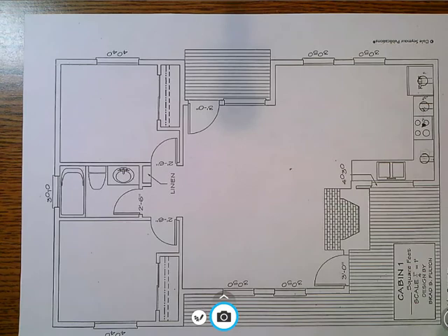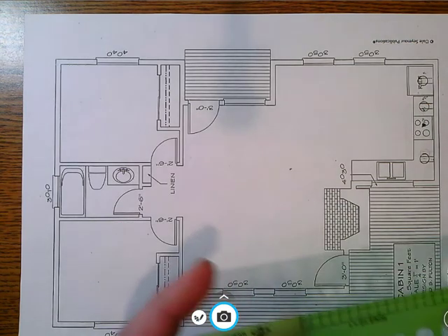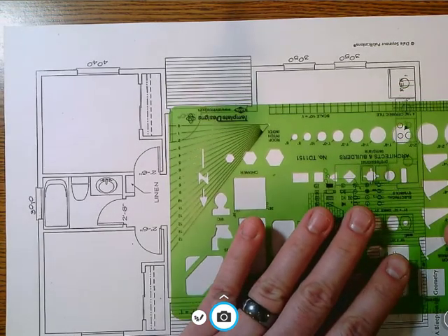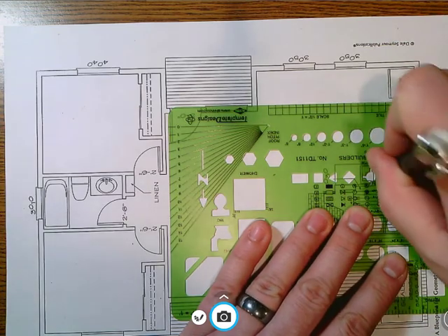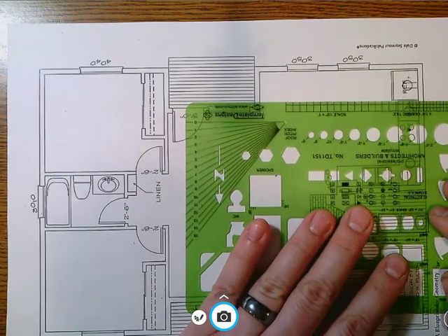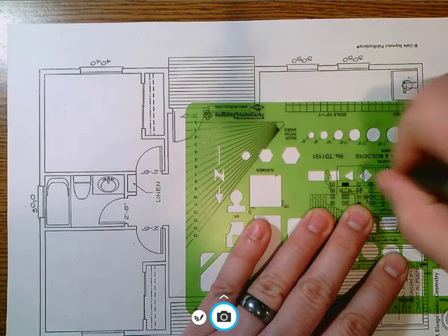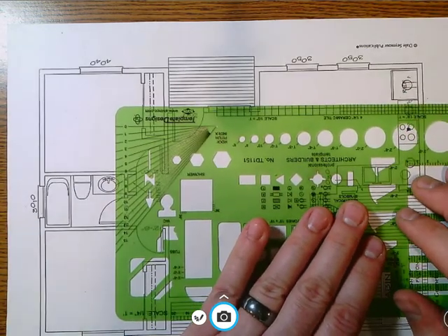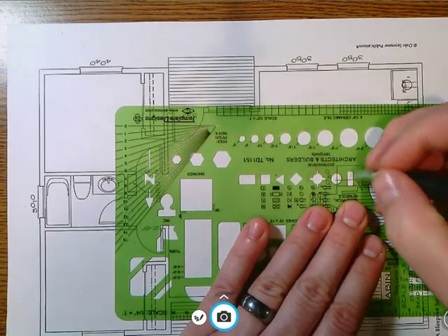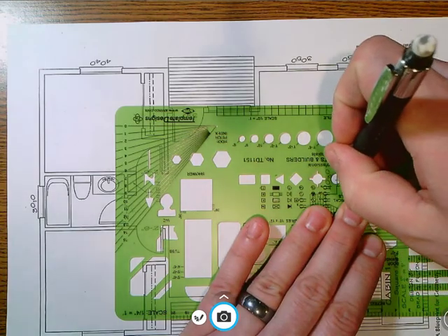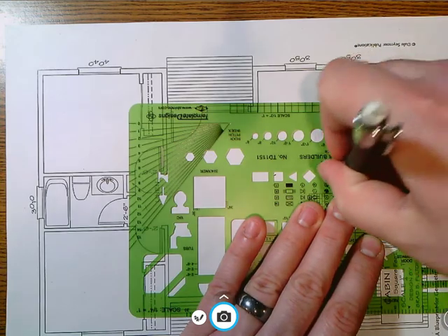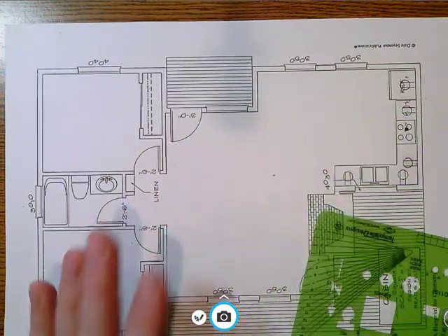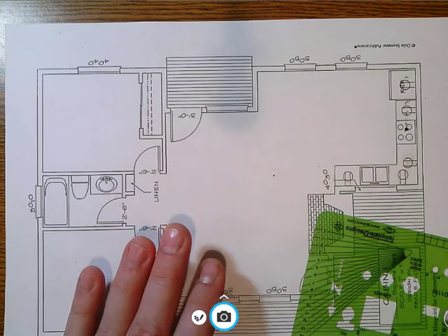And more doesn't always mean more. I'm going to stress that you don't need to go stir crazy with the number of outlets that you have here. We're going to have one here on this side of the window, and then draw the circle. And then we'll have one over here on the other side. These would probably be GFCI outlets because they're next to water. And now we're all set in the kitchen as far as our 120.